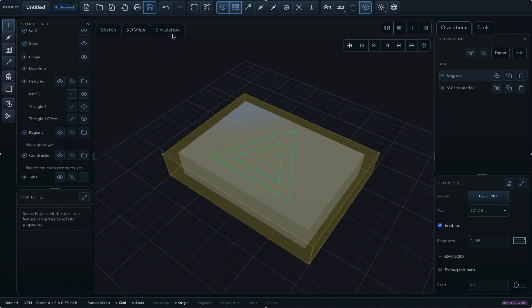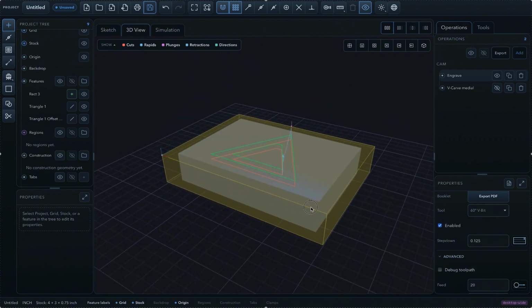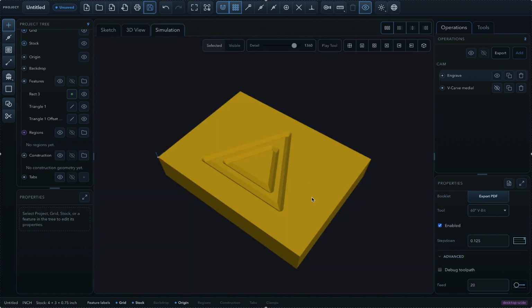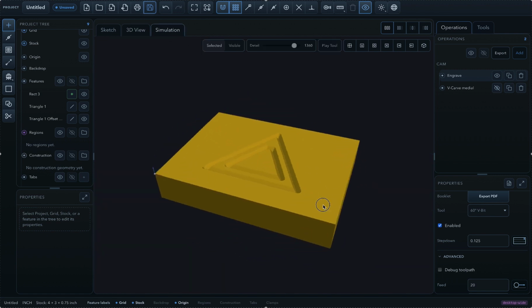The cutter follows the geometry itself at the selected engraving depth, using the operation step-down and tool settings. A closed line can also be followed around its contour, but PureCutCNC will not clear the interior simply because the path forms a loop. The Z detail is especially important for lines.